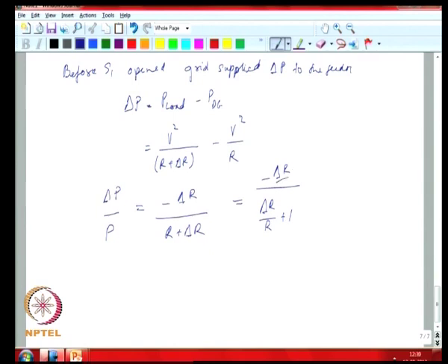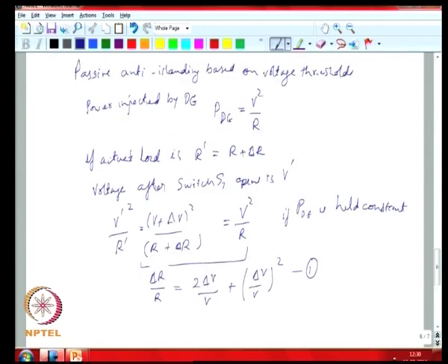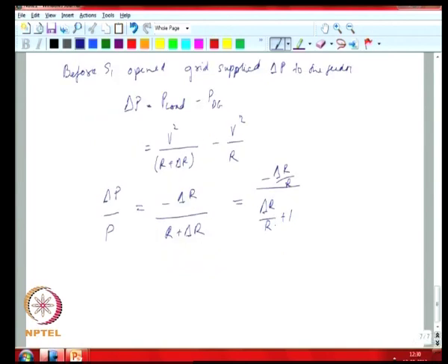So, you could take the expression for delta r by r from the previous page and substitute it in this particular expression over here, and with further simplification you can then express your delta P to be equal to... So essentially we can relate the delta P and the voltages on your circuit, and we could consider V plus